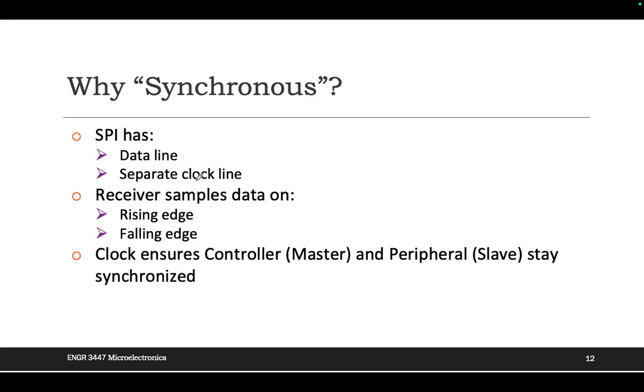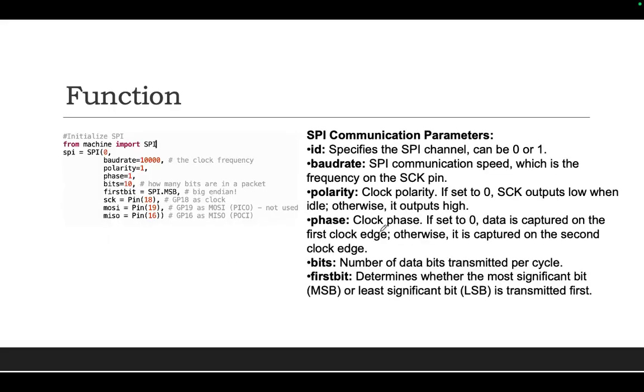Okay, and then why synchronous? You can see SPI has a data line, and also a separate clock line, and the receiver samples data on the rising edge or falling edge. It depends on your configuration, this one, the phase.